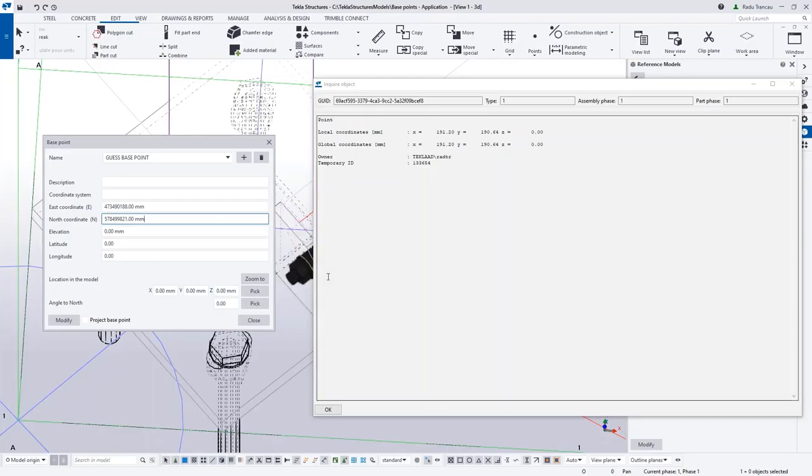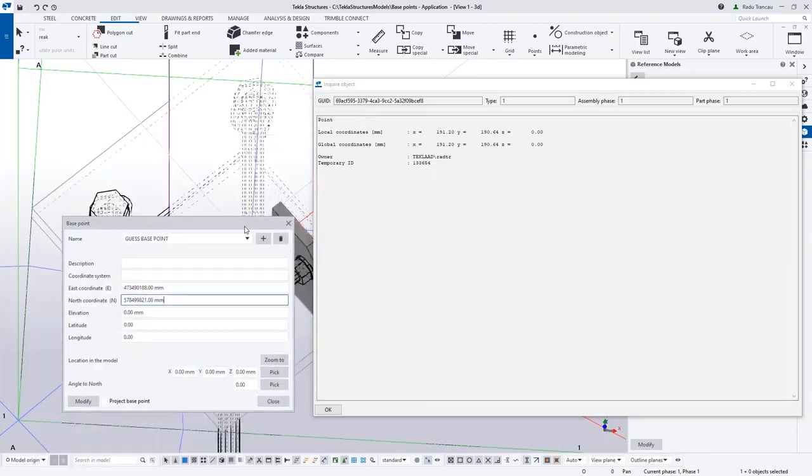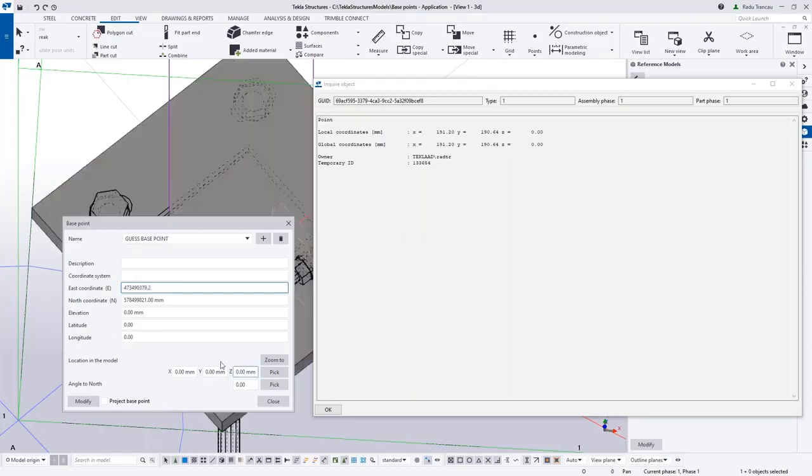Okay, so this is how you bring that point bang onto the Tekla origin. Let's just quickly put in the values here. So that would be 490,379.2, and then that will be 578,500,011.6, if my math is not wrong.